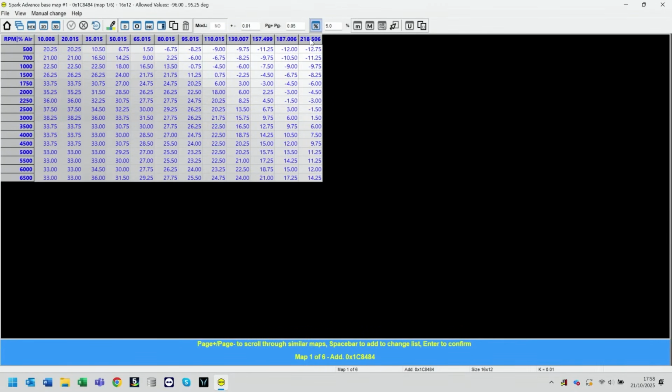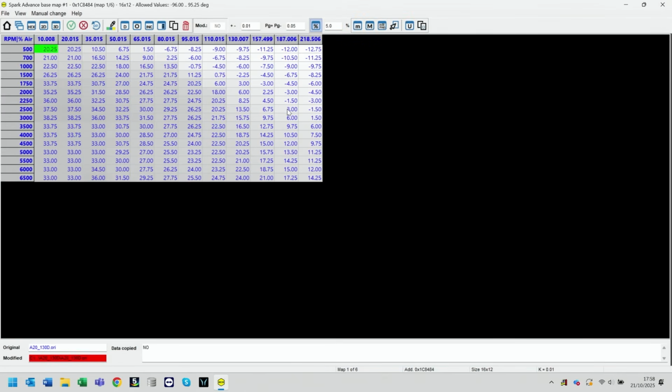So what we've done, we would then effectively have to start making changes to the previous columns to bring them in line with the logic and strategy of the ECU. Some people do this even in Excel. They'll build a table in Excel and start making the changes in there. Obviously there's other software you can do that with, but we can start to make changes here. So effectively take these values and put them into this column, meaning that we do have control for the correct values at 190% of air.